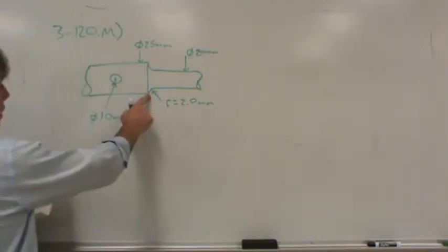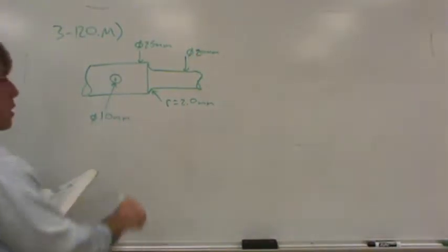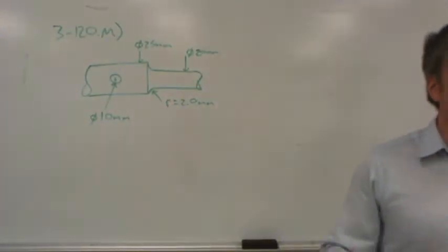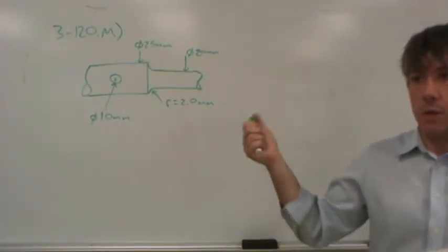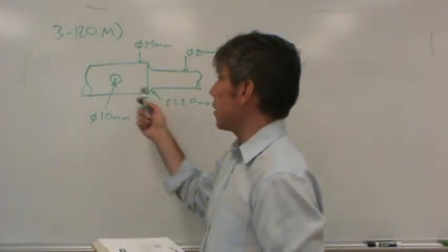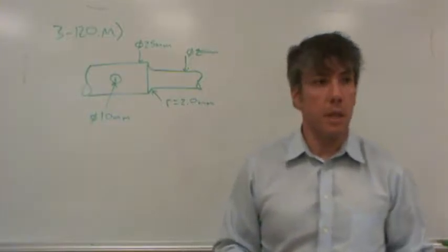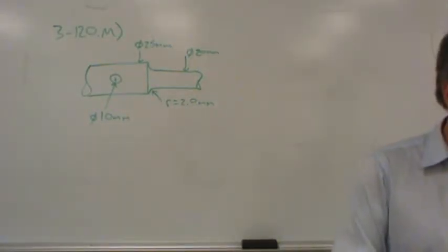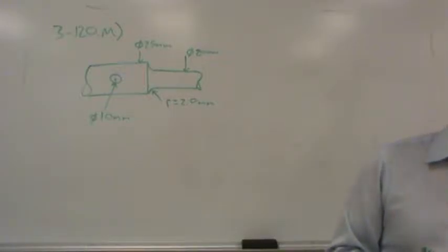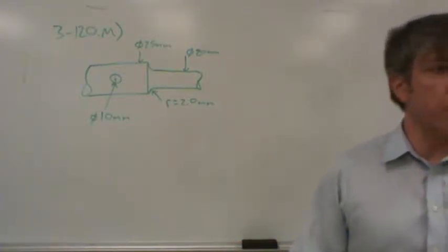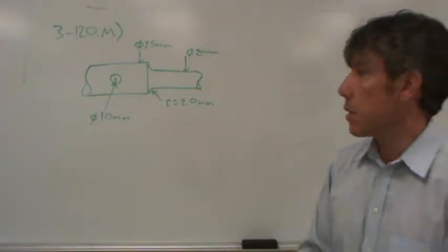So there's going to be stress concentration here, there's going to be stress concentration here. The question is, what's the design factor? In other words, how close is this thing to failing at those 2 points? Why would we care? Well, the one with the lower factor is probably where the thing's going to fail, right? So we'd like to know, is it going to fail at the fillet, or would it ultimately fail at the hole? All right, so let's start off getting the stress concentration factors, because you realize we're going to need that, right? So let's just go do it.